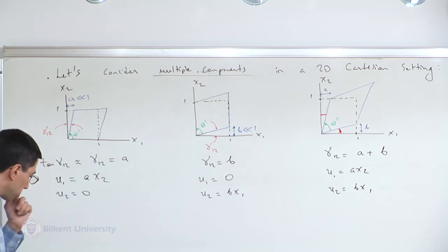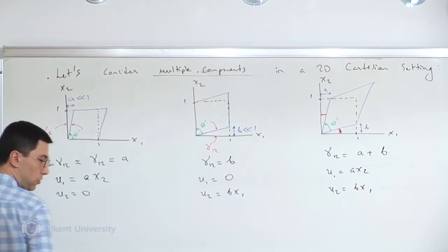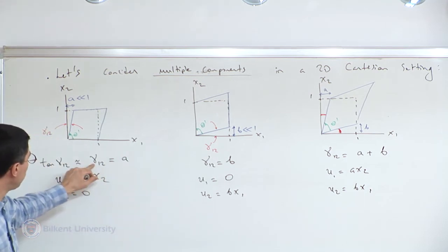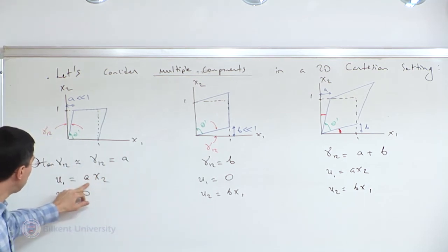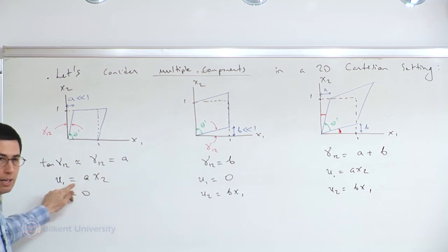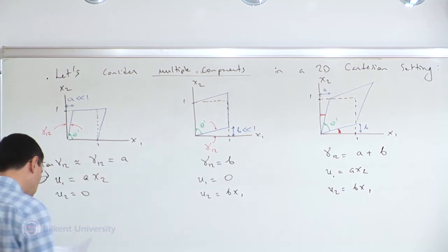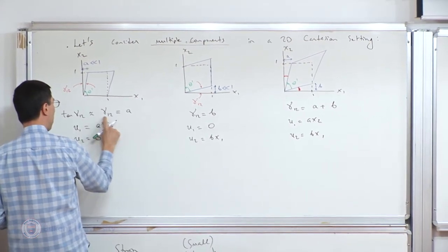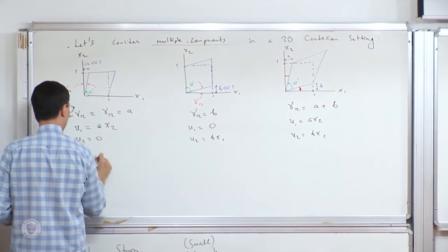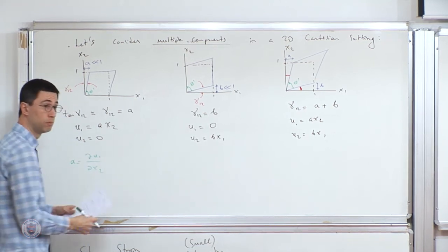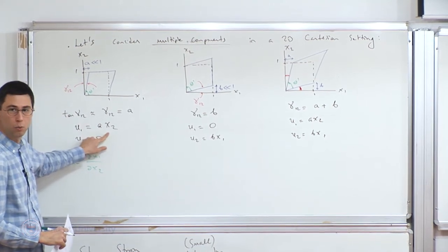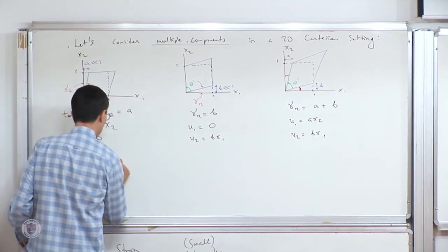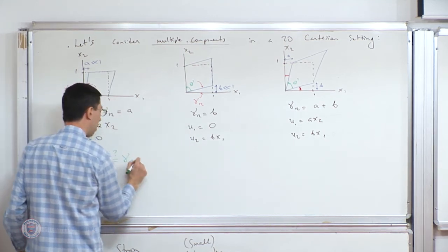All right. So now let's start. I know that this is the result for the shear strain. Now I try to relate it to the displacement field. And I just try to do a simple observation. My observation is that A, which is gamma 1, 2, is del U1 over del X2. Right? It's del U1, del X2 that gives me A. So I suspect, is this equal to perhaps gamma 1, 2?